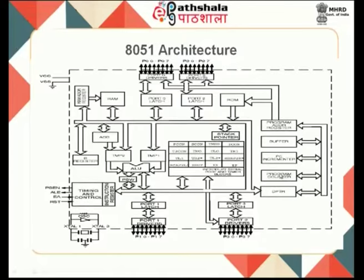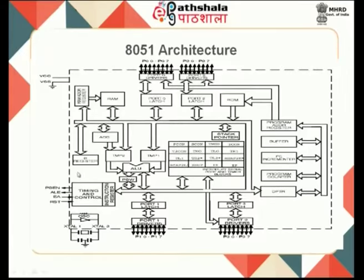So, a 16 bit address will be sent through this, and we will have a program counter. This will be used for holding the address of the next instruction, and we will have a PC incrementer. So, each time I get an address, I will go and fetch the data, and I will come over here for data or instruction, and this will come to my instruction register. From the instruction register, the instruction is decoded, and the timing and control unit will send control signals to all the parts of this architecture.